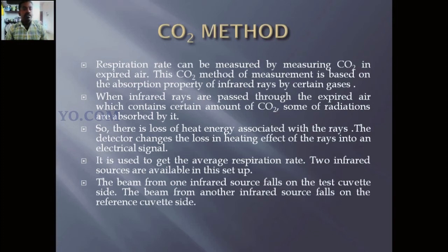The respiration rate can be measured by measuring CO2 in expired air. This method of measurement is based on the absorption property of infrared rays by certain gases. The CO2 measurement depends completely on absorption.